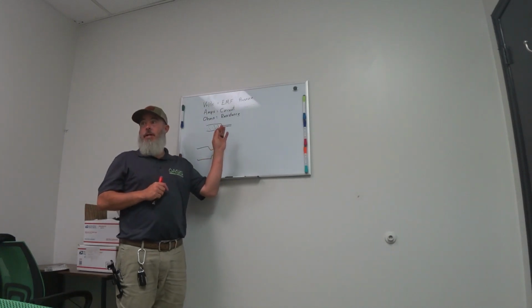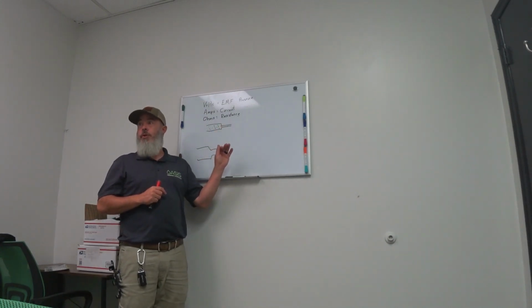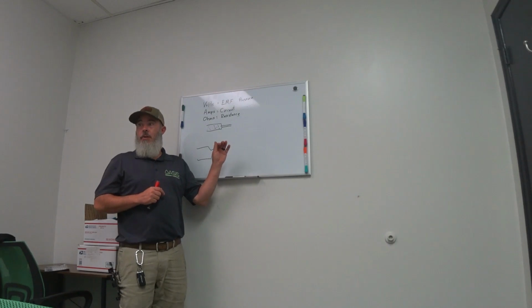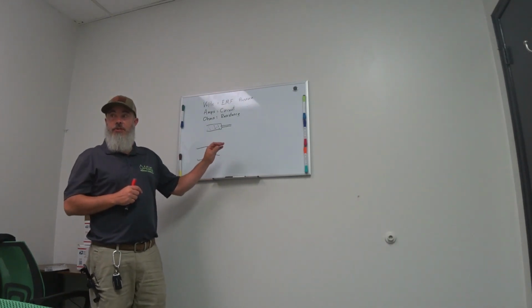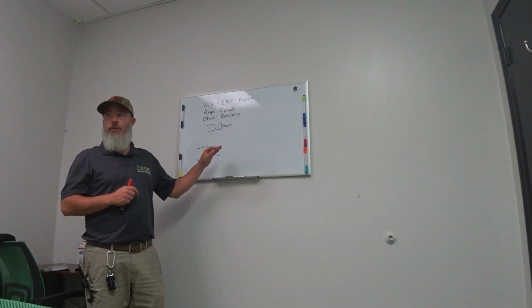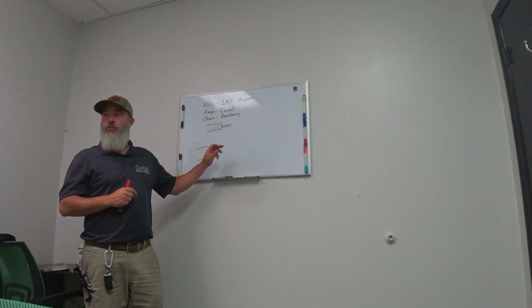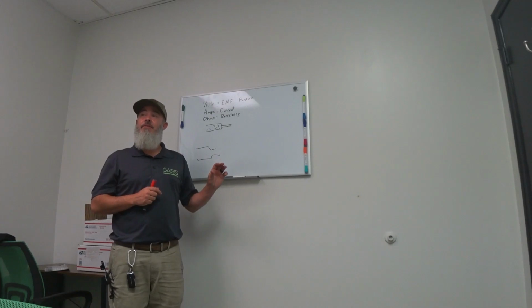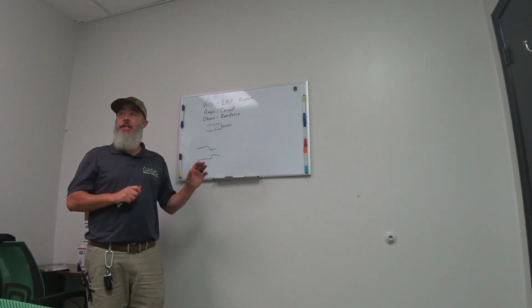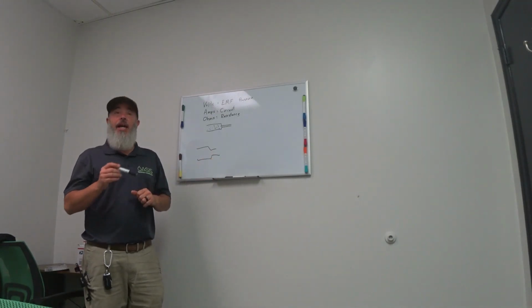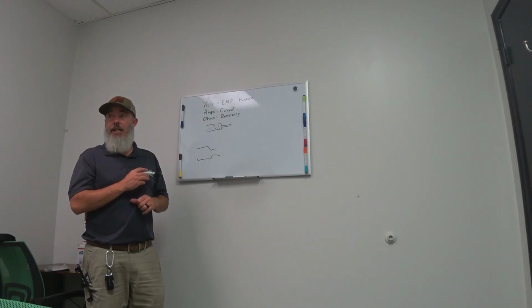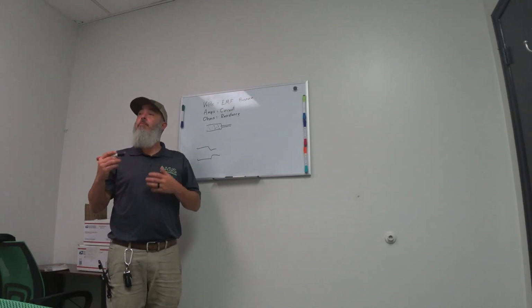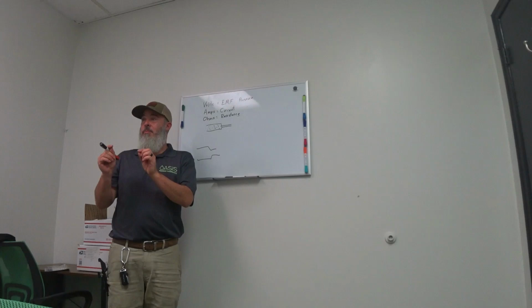So like, we typically talk about 115 to 24 volts, right? But you'll see in our ice machines, sometimes we use 24 volts, but there's usually a little transformer, especially in the Hoshizakis, that brings it down to 10.5 volts. And it's still AC, 10.5 volt AC. The reason that you step it down to 10.5 volts is so that the board can pass power according to its logic.